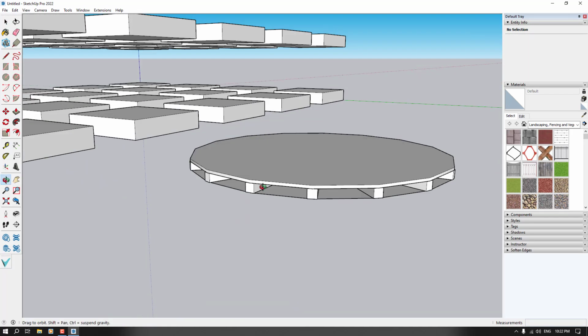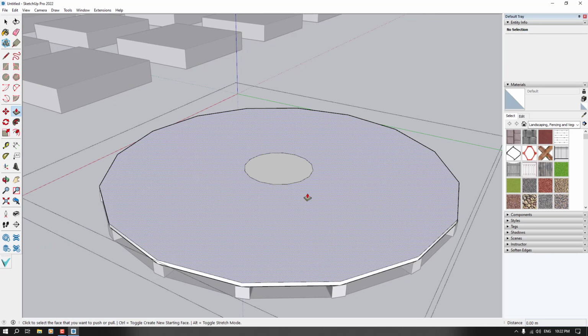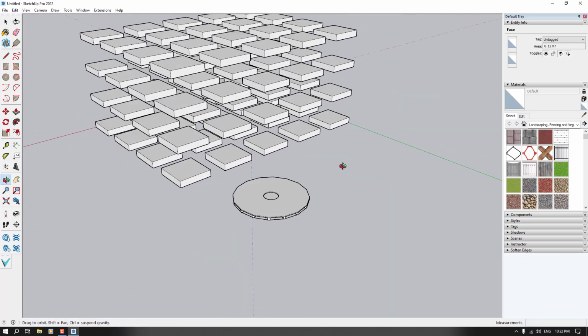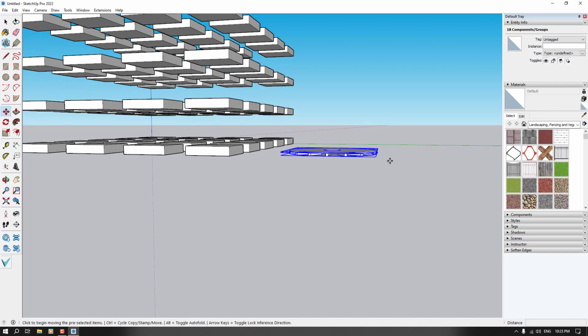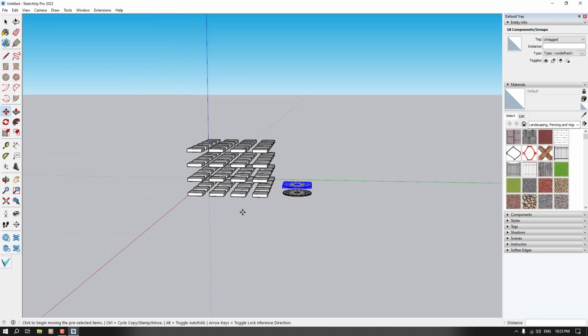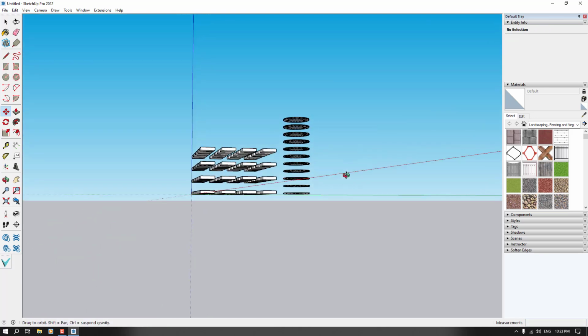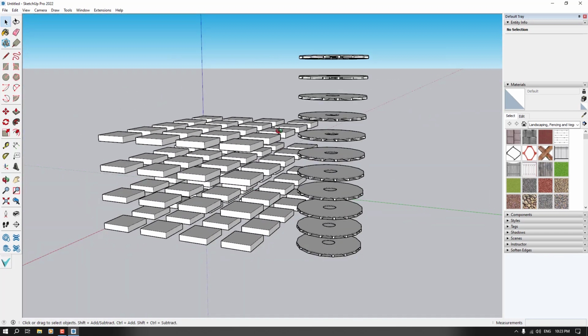You can see this type of wooden pallets in ocean docks or other places in industry. You can create some type of offset of it and you can remove it again. So as you can see, we create these type of things in SketchUp only with the copy option. At the final, you can take some other copies on the blue axis with some dimension related to you, and it's really manual. For example, I want 10x copy, I can type 10x. As you can see, we create these type of shapes and models very simple and easy.